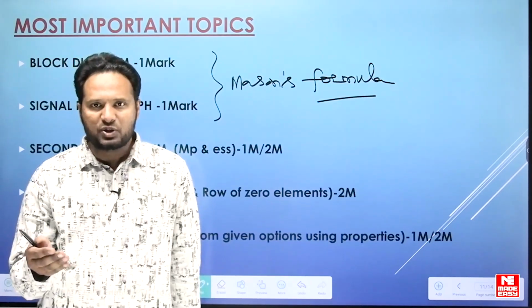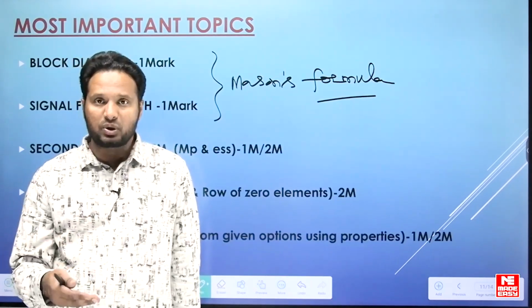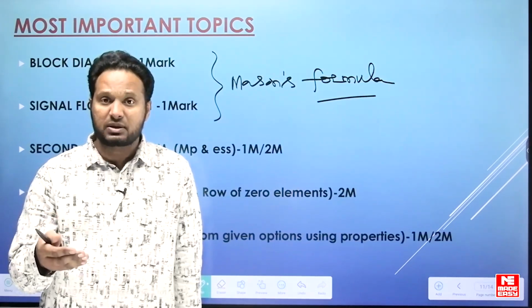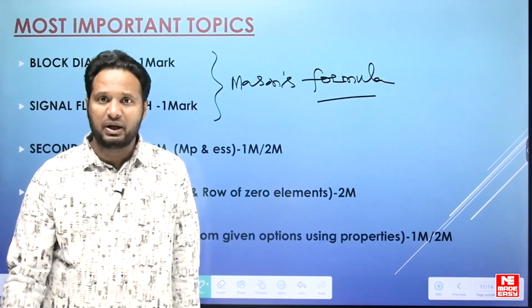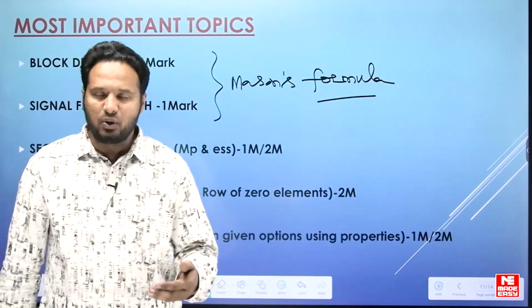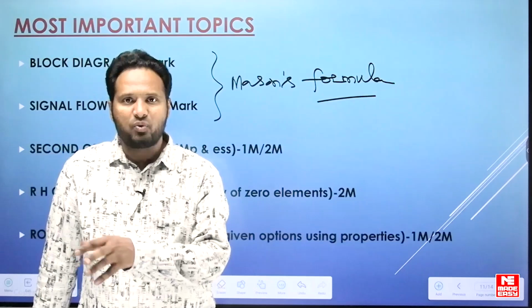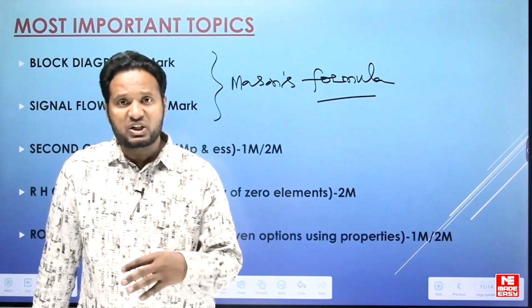Like in the case of root locus plot, to obtain the root locus, start from the fundamental properties. It has to be symmetric to the real axis. Whichever is not symmetric, eliminate that. Then, small properties one by one: the root locus has to be on the real axis to the right of an odd number of open-loop poles plus zeros. Whichever is not satisfying, eliminate that.